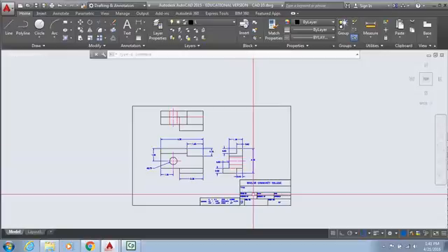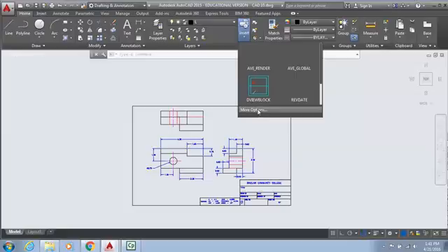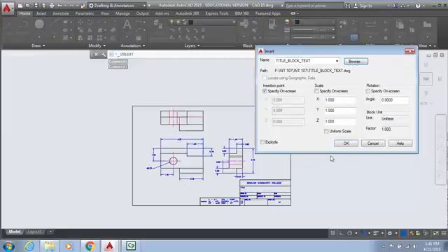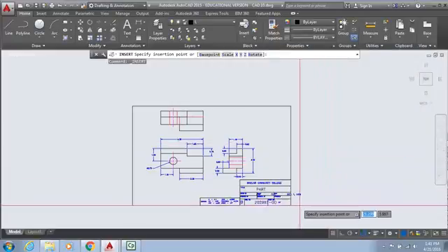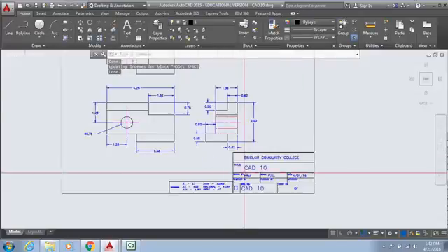There's your border. Let's insert your more options. Go to browse, title block text, open that up, hit OK. The corner's right there. The part is CAD 10. Caps lock's on. CAD full. It is 4/21/16, and this would be CAD 10. And OK, and verify that that's there.